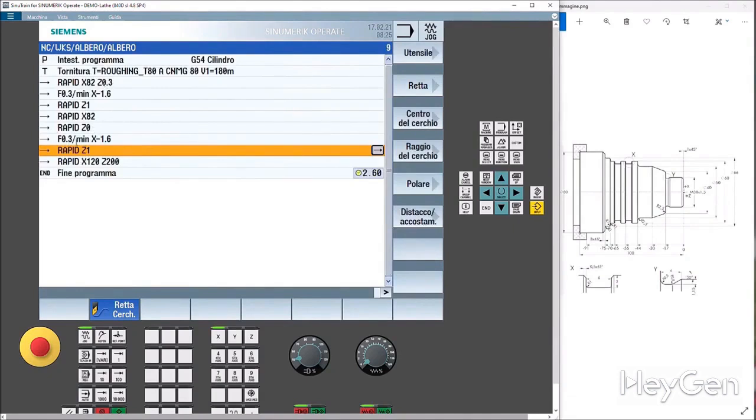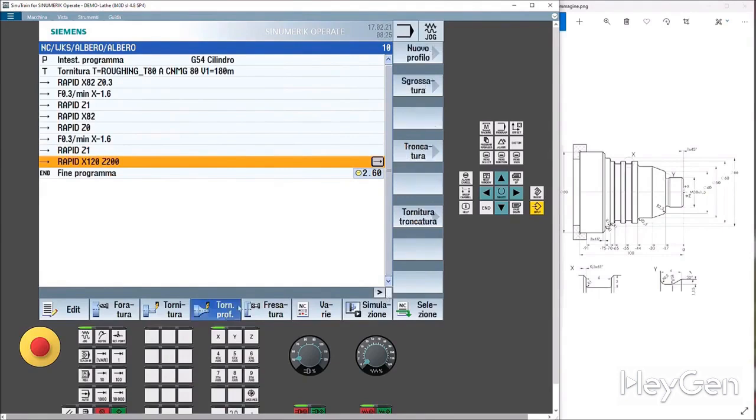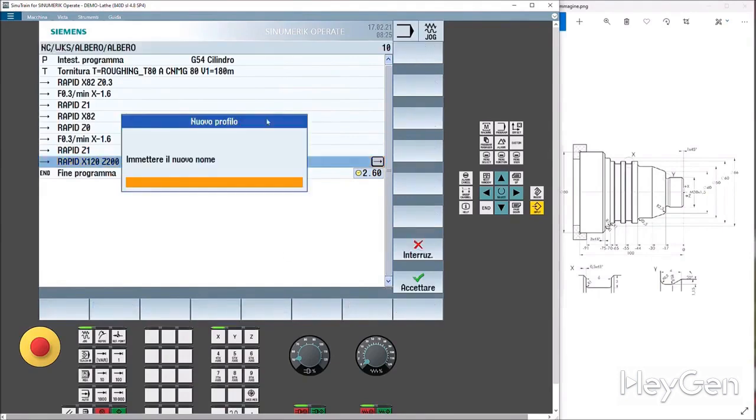Accept the profile. So I'm no longer starting from X0Z0, because honestly, starting and finishing from the center of the piece will almost certainly lead to incorrect wear of our product, but I'm starting at X25Z0. You see here, it asks me how I want to finish the next movement, chamfer, radius. If I set it to 0, it won't do anything, regardless of what I've written here in the automotive section. Lately, I'll show you this only once. It's always asked to put a small radius at the end of each movement. So radius 2, because the piece will look nicer.